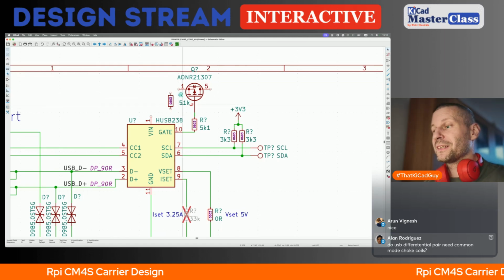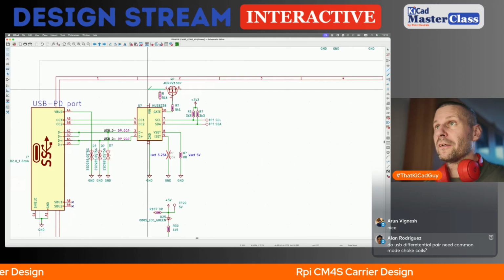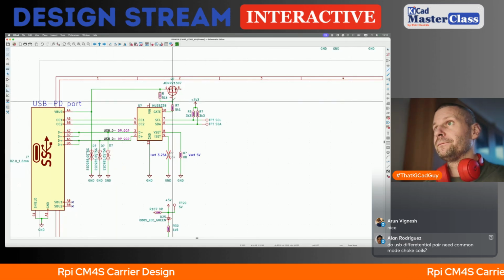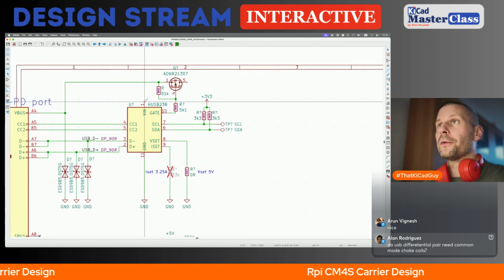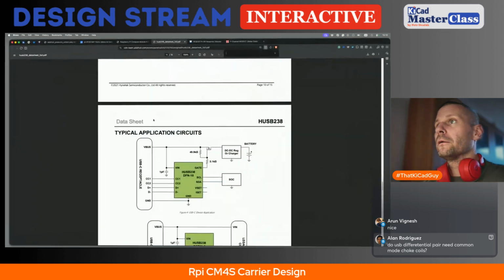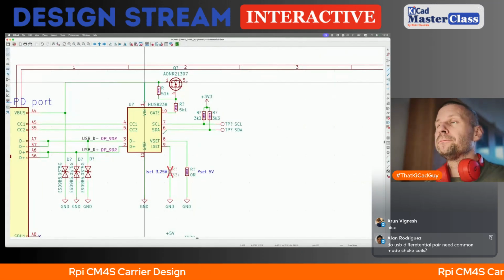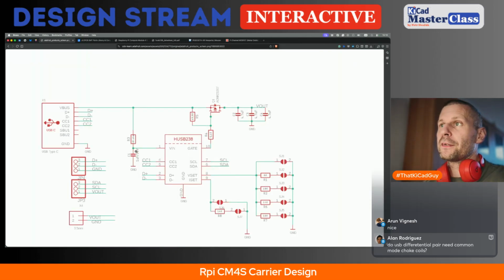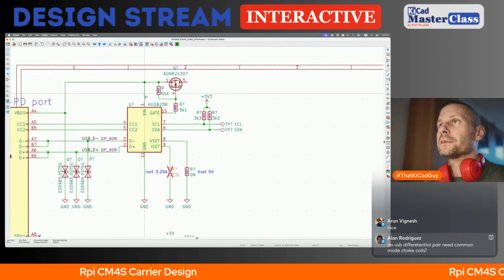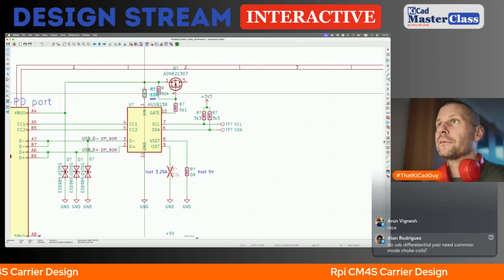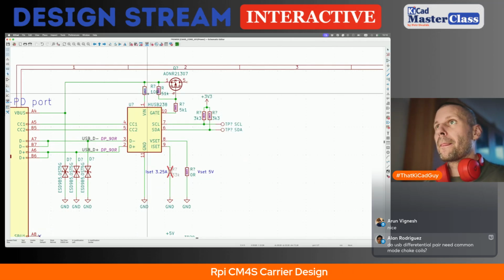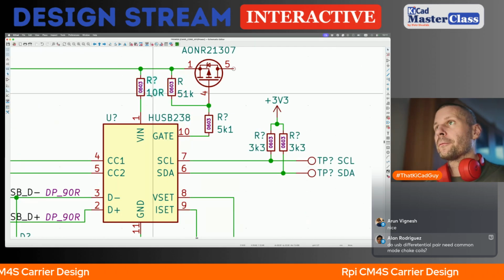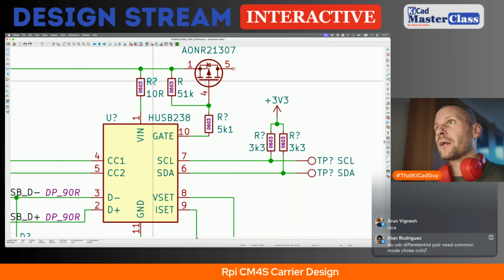This FET doesn't set any output voltage. It only enables the output voltage of the VBUS. Yeah. So I think there is no point of overcomplicated thing with it. And they say, yeah, there is like, yeah, that's definitely a good idea. I like it. I like it. Yeah, that's always a good thing for limiting the short circuit current if anything happens.